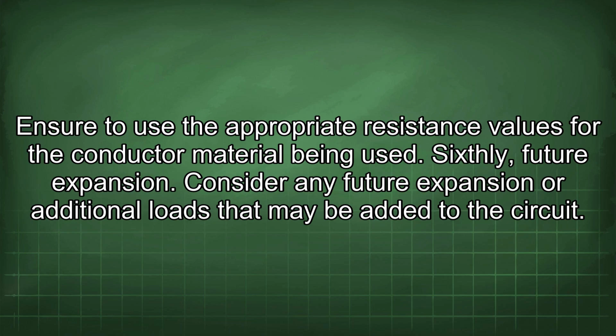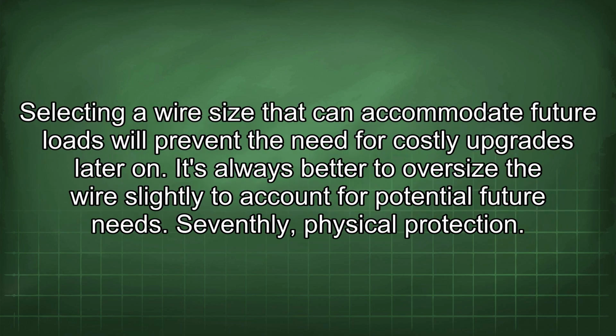Sixthly, future expansion. Consider any future expansion or additional loads that may be added to the circuit. Selecting a wire size that can accommodate future loads will prevent the need for costly upgrades later on. It's always better to oversize the wire slightly to account for potential future needs.